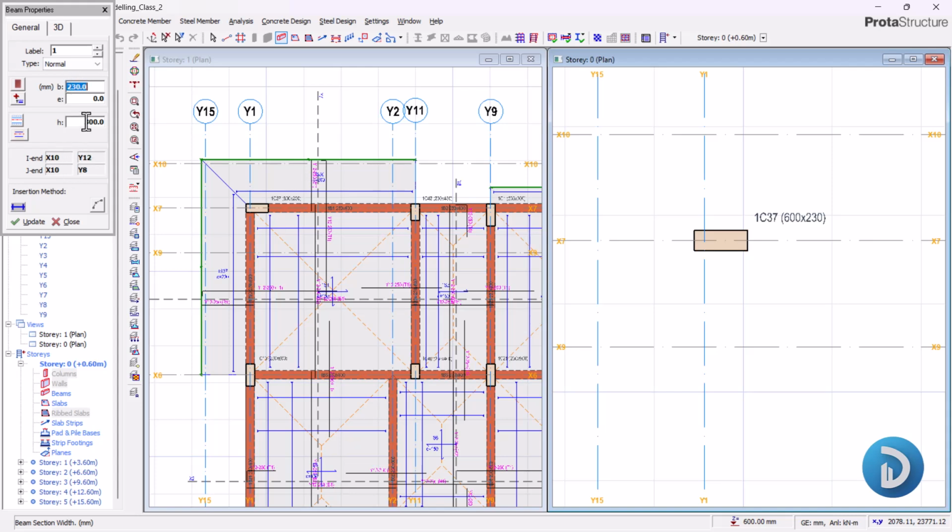While for the thickness, it all depends on various factors like the water table of the site, or let's say that they intend, or you intend, to raise this structure to a specific level on that very site. You can also get that information. Or during the soil investigation, it was advised that we raise the foundation to 1.5 meter above a specific level. So this is the factor that can affect the depth or the thickness of your beam.